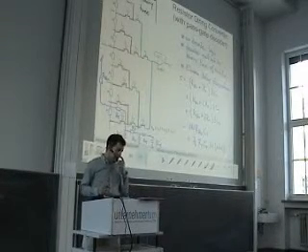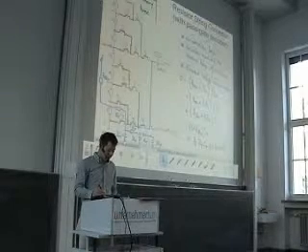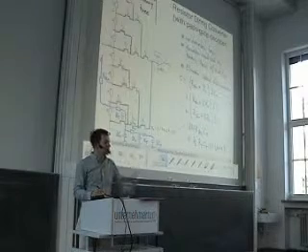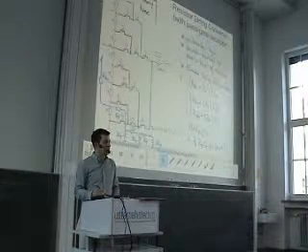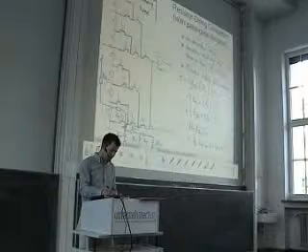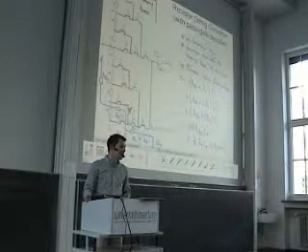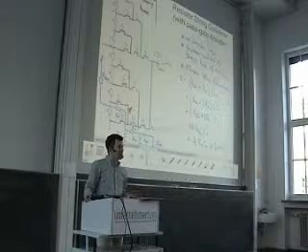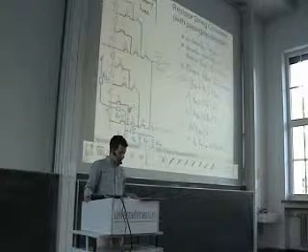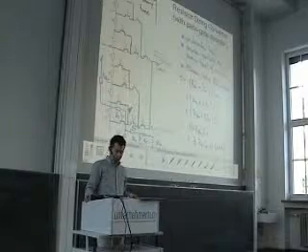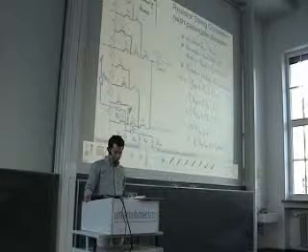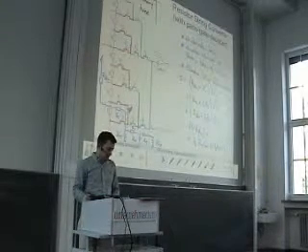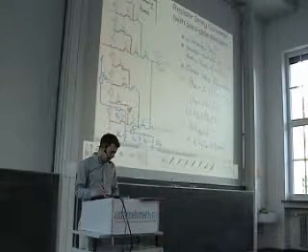Why? Well, because then the effort explodes, because for each step you need a resistor and you need a switch transistor, or you may need even more switch transistors in this tree architecture. And then there are other architectures, so-called binary weighted architectures, that I also discuss today, that can be used instead. Okay, the question is, how can we combine the advantage of these two architectures?